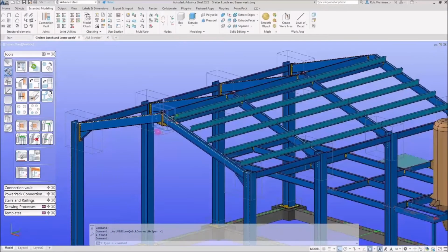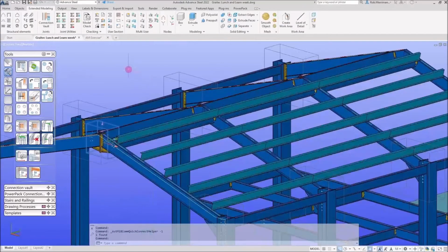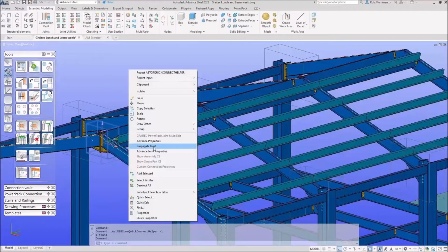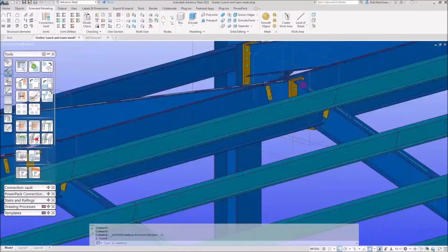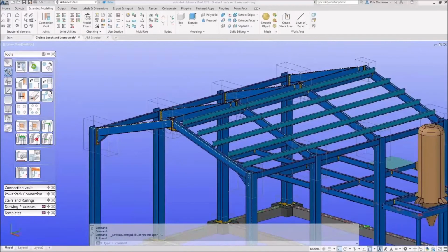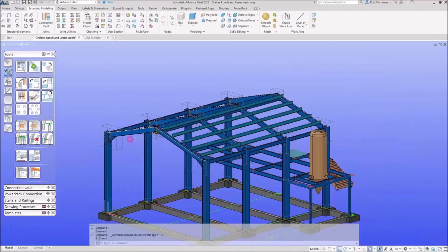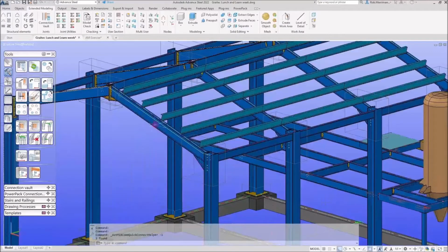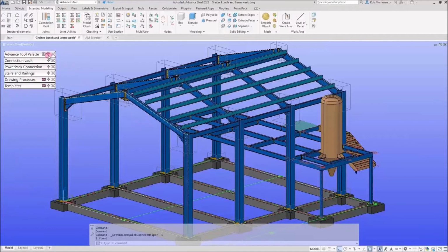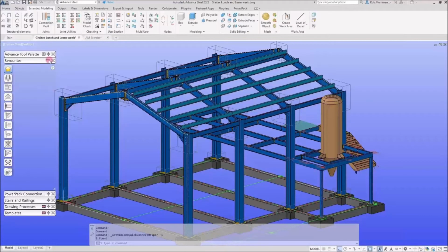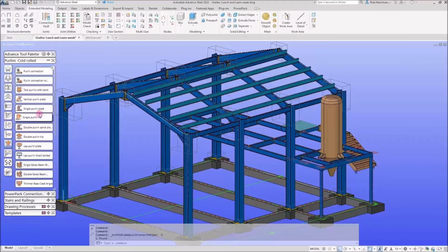If I select the joint box, and go propagate joint, the system will put those joints on automatically. Now, for these sorts of connections, propagate joint is excellent, in my opinion. Some of my other colleagues in certain scenarios don't like propagate joint, and I would agree with them, and I would like to explain why and what the system is doing in certain scenarios.